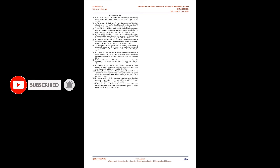4. Mutation. Crossover operation results in reproduction of offspring. This is also termed mutation. In this process, the main aim is to create a new children chromosome pool. The members of the children chromosome pool, however, must satisfy the conditions of optimal objective function values. If the offspring fail to satisfy the constraints, then they are eliminated from the pool. The quality of the offspring can be improved by changing the parents for the crossover and mutation process. The offspring then indicate new settings of the relay. This process is continued till the total number of generations criterion is met.